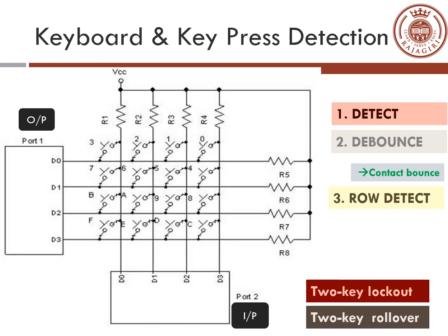The circuit shows a matrix keyboard with 16 keys. If we arrange the keys in a 4x4 matrix, then we need only 8 wires from the microprocessor to do the keyboard operation. If we did not arrange it as a matrix, we would have needed 16 separate wires. So arranging it as a matrix helps us to reduce the number of wires required.